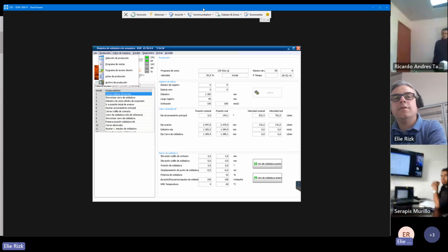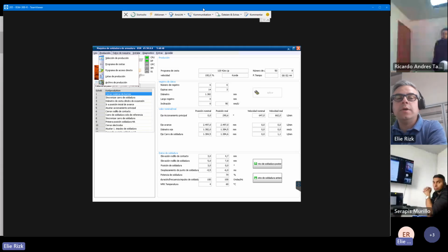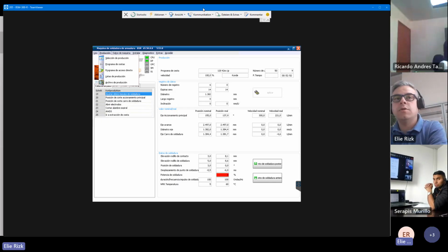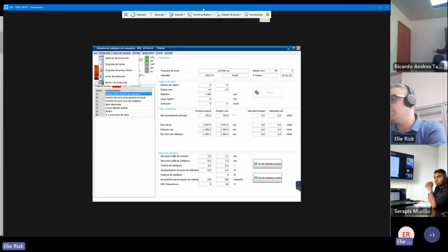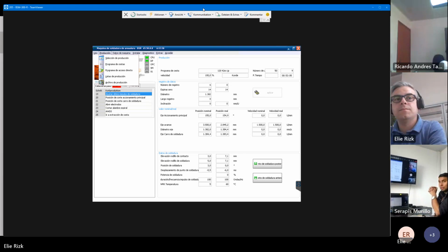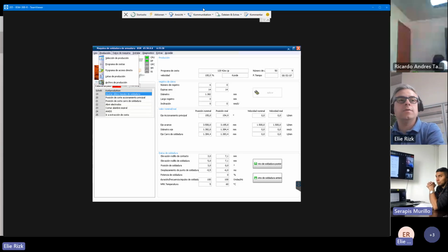We set it to 20 degrees, 22 could be okay too. So the water which should be coming to our welding roller or contact roller or transformer should be in this range. So 20, 22 degrees should be okay. This is your question, right? Yes.